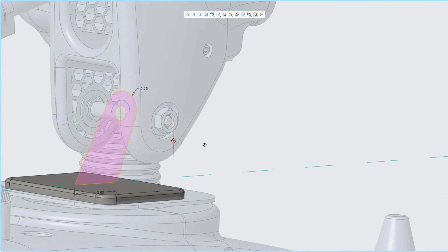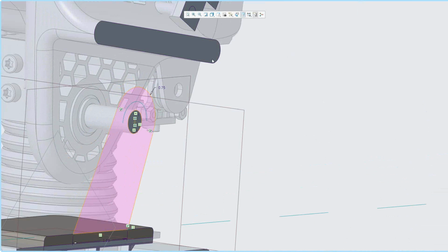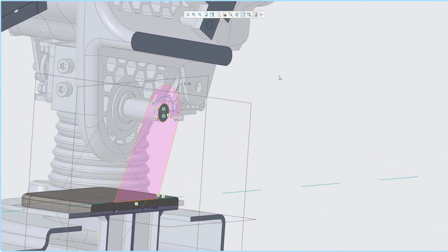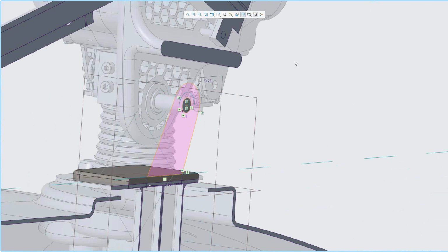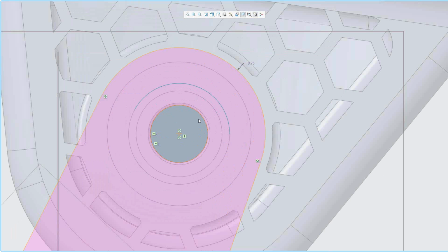And so with clipping at your sketch plane, what that basically does is this: you click on that button, and you can almost think of it as creating a section temporarily of your model at your sketch plane. So that way now it chops off all of the overhanging geometry in front of your sketch plane, and now you can directly see any geometry or references you want to select and base your sketch off of.